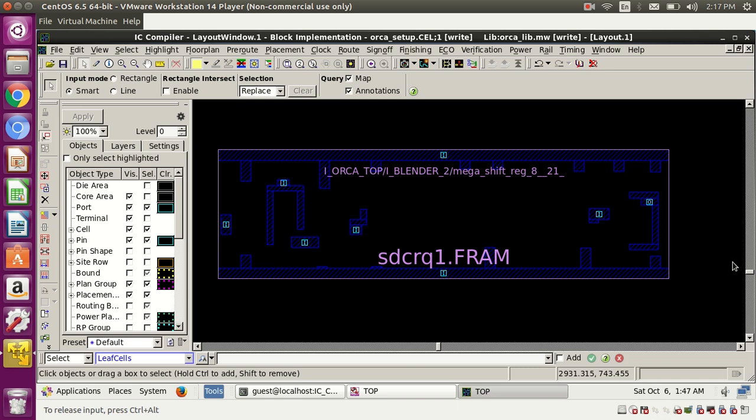In the clock path it will come from the root clock pin to the input, through clock source latency and all those things, and then it will come to CK. So you just check what's the value at this CK and what the value is at that CK.